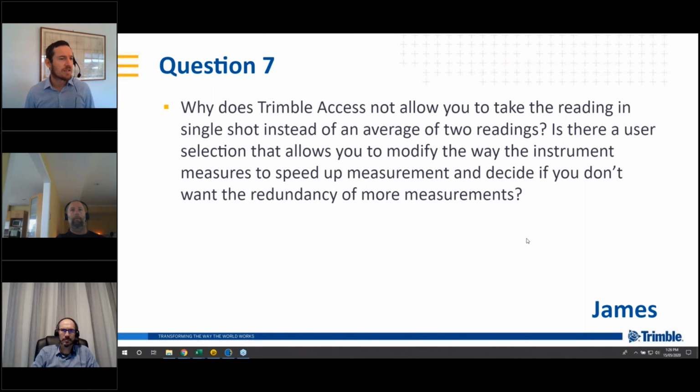You can switch that to tracking, which gives a constant distance feedback at a much higher rate of measurement. So if it wasn't relating to measuring on face left and face right, or face 1 and face 2, and was relating to the actual amount of pulses, we do support a tracking mode.